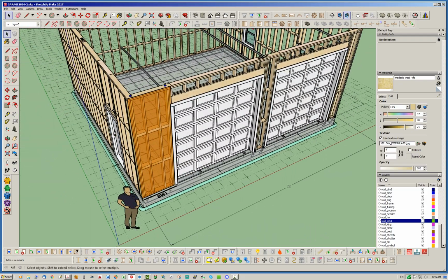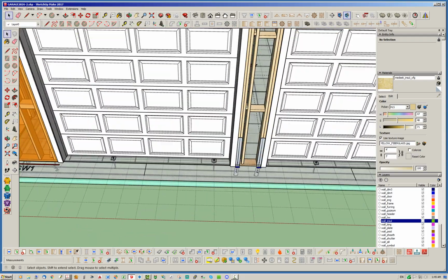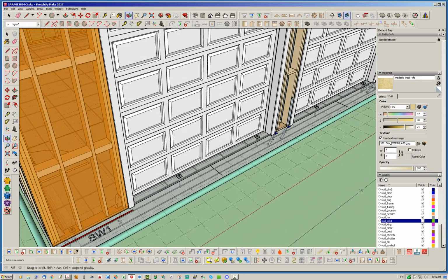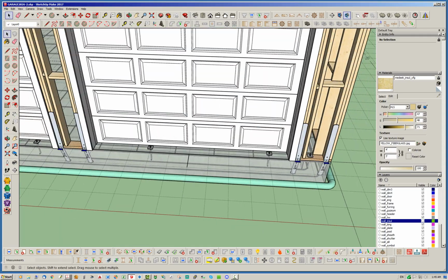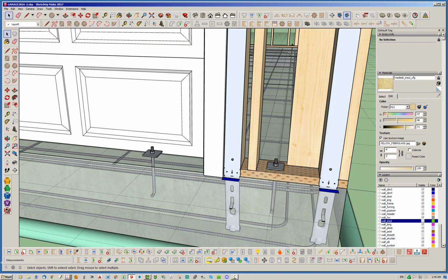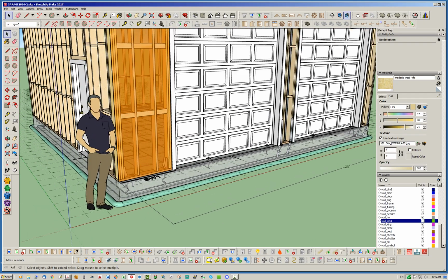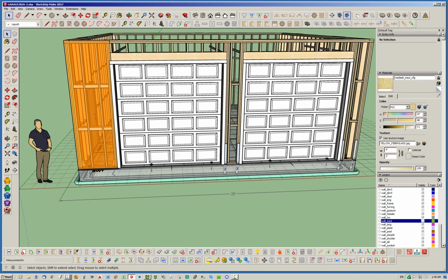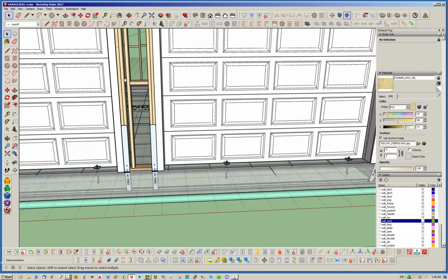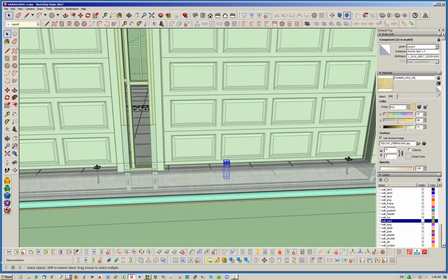Okay, so let's go over here now to this wall and take a look at what we've got. Same sort of thing going on. We've got 2 anchor bolts floating around in here, and we've got quite a bit of anchorage there. I would say that one anchor bolt's good enough as it is. Maybe drop an anchor bolt here, maybe drop one more anchor bolt there. So let's just delete that one, delete that one, take this one, here, 3 foot 11 inches.